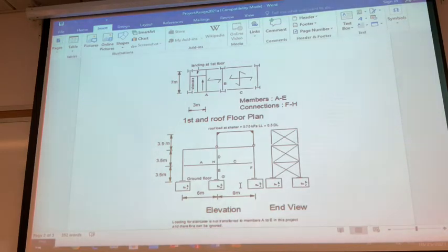If I have the opening, then I should have the secondary beam. The secondary beam supports that. So I just write this beam has a lateral restraint from the secondary beam. Same for this one. And I also have the bracing. It's a reminder: the bracing cannot be applied or installed in this phase. You can only apply it at the end.